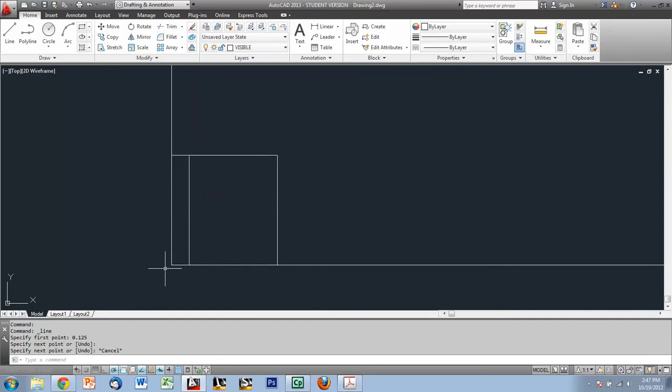And I'm going to do the same thing to create a horizontal line that's 1/8 of an inch up off the bottom of the square. So I'm going to use the line command again. I'm going to O-track to this point just by hovering, move the mouse straight up, and I'm going to type in 0.125, hit enter, and you'll see my line starts exactly where I need it now without having to draw any construction lines. And I'm going to come straight over to the right and click again, and then hit escape. And now we have those two lines spaced out exactly where they should go.